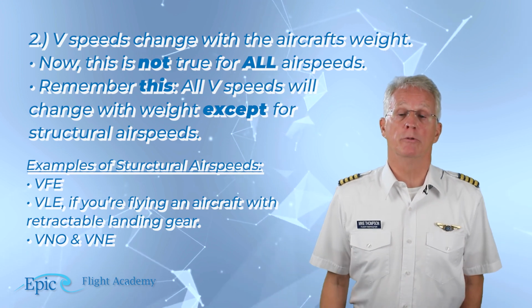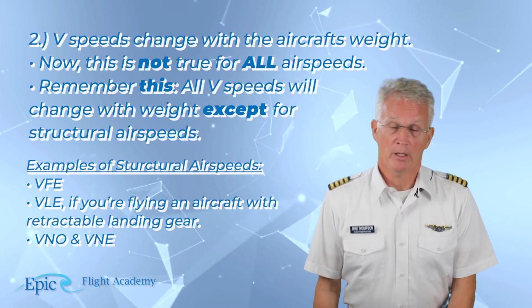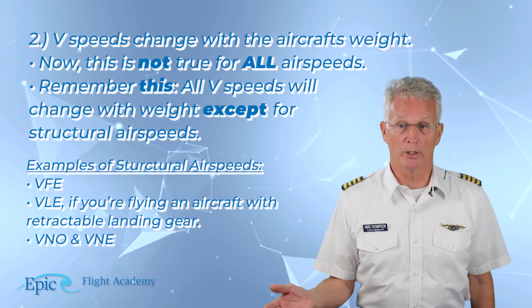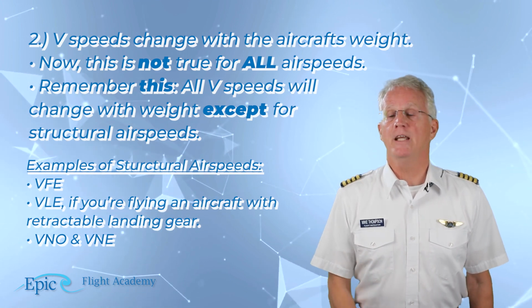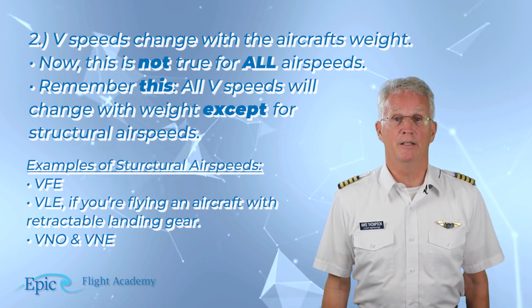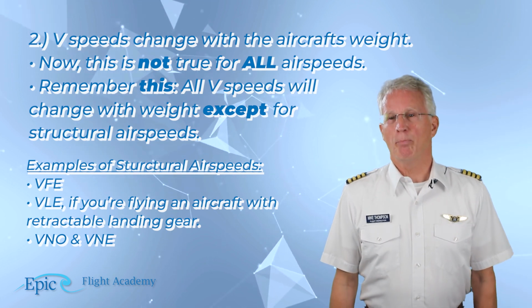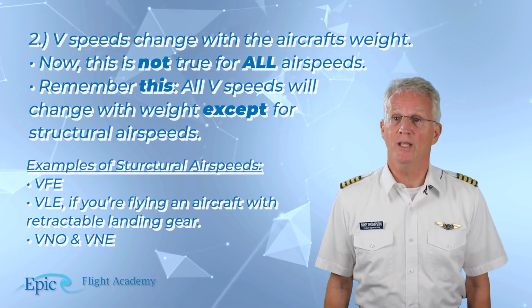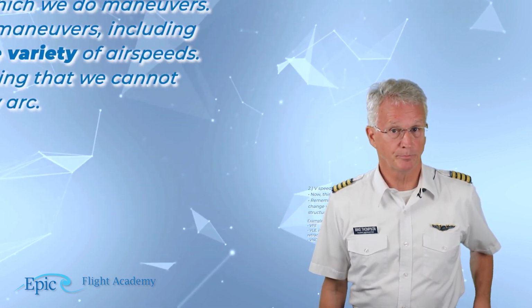Well, examples include VFE, VLE, if you're flying an aircraft with retractable landing gear, VNO, and VNE. An important airspeed to remember that changes with your weight is VA, or maneuvering speed.